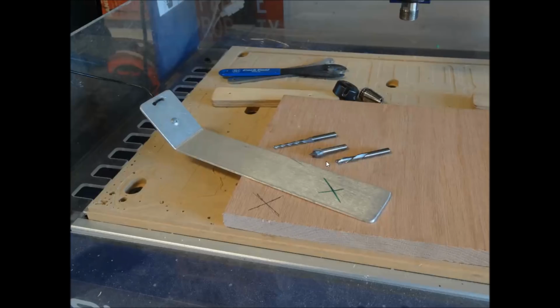So what I like to do on parts before I run them is, if I'm going to have multiple bits, I like to put an X somewhere on my material that's not being cut away. Or on my spoil board, if that's something that I want to zero there, I'll put an X on the spoil board. And then every time I change a bit, I move to that location, and you can set that up in your file like we previously saw with our home position in the CAD software.